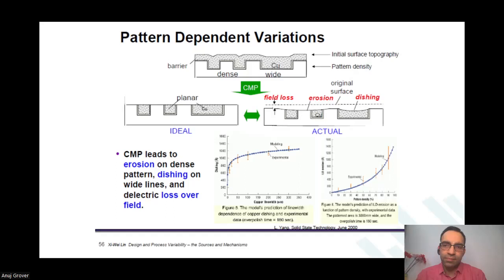Yes, sir. We talked about the race conditions in the IO. That was the last slide we discussed. We saw that in the IO, the precharge should come before the word line. We saw this race condition. What does this mean? That the RC of the precharge signal should be similar to that of the word line, or at least there has to be some deterministic relationship between the RC of the word line and the RC of the precharge signal.